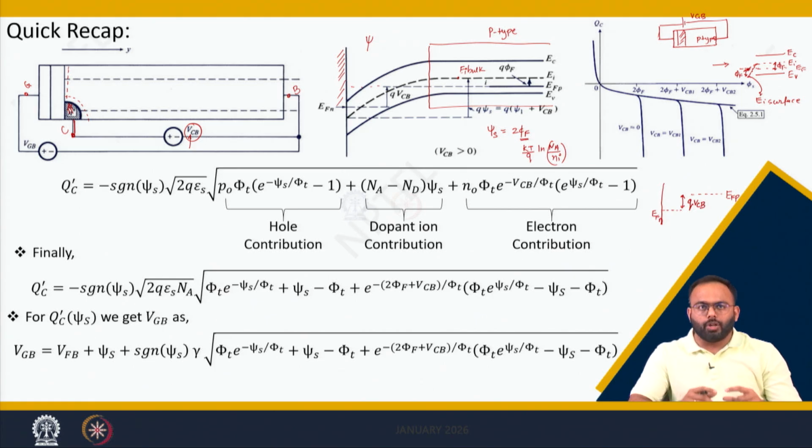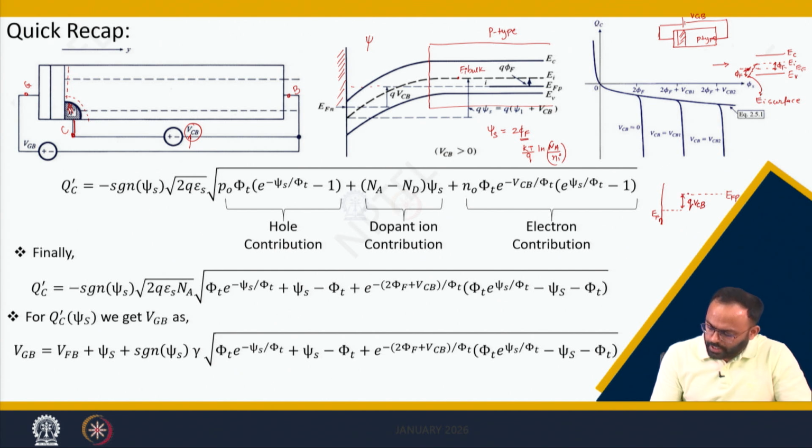So, the applied voltage between C and B is nothing but the split in the Fermi levels, and these Fermi levels are called quasi Fermi levels. Now, if you want to measure the total bending, let us say this is EC and this is EI, right.